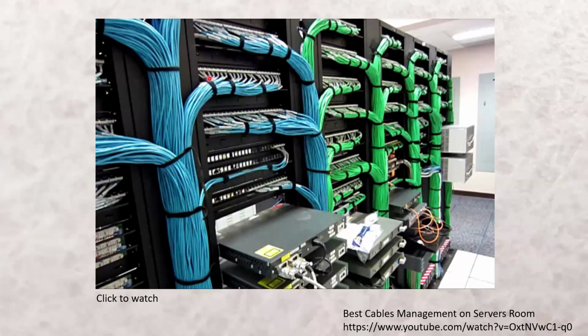So on one side, at the location, at the desktop, underneath the countertop or something like that, you have a female RJ45 or data Ethernet jack, which is terminated, and the line runs right to the patch panel, where it's also terminated at a female Ethernet jack.